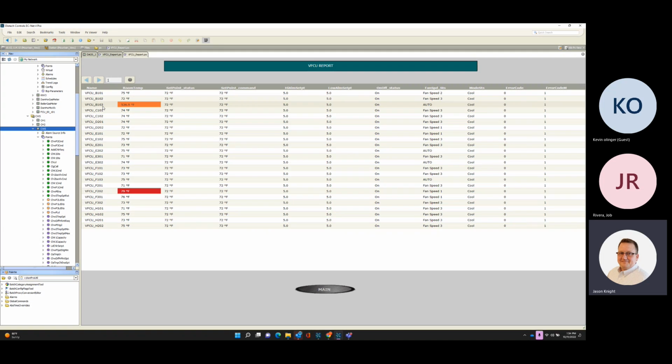It was actually DOAS 6 and Air Handler 14 that were overridden on. It wasn't actually DOAS 6 that was keeping the logic on, it was 14. Okay. 14 has a chill water valve. And so it was calling for cooling, trying to cool all night, and it kept the chill water plant on. And then DOAS 6 was overridden, and it affected